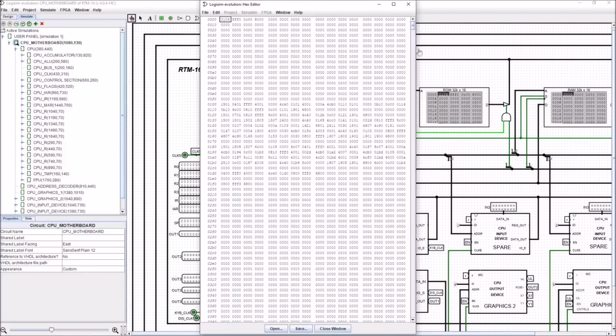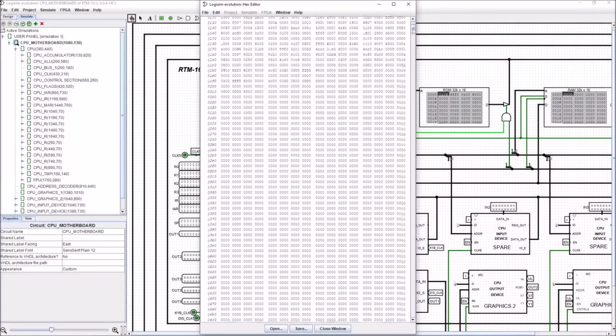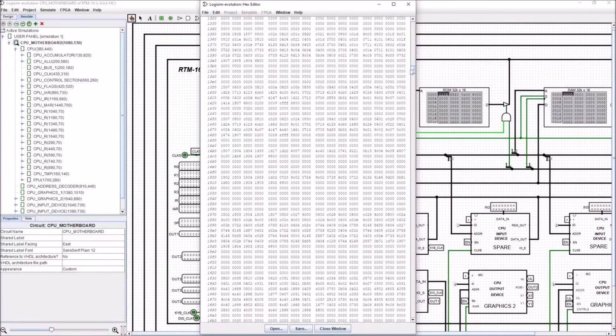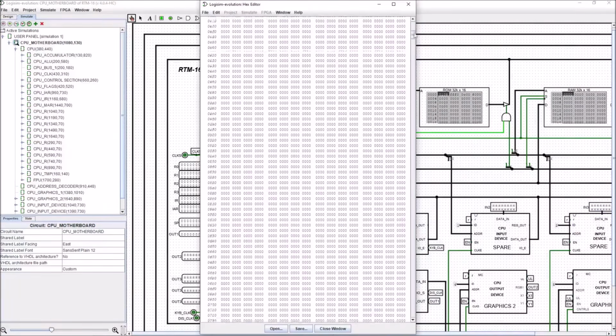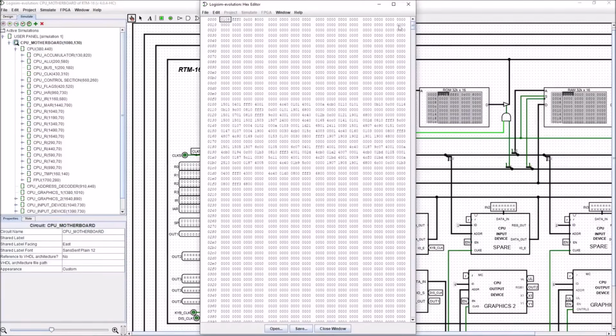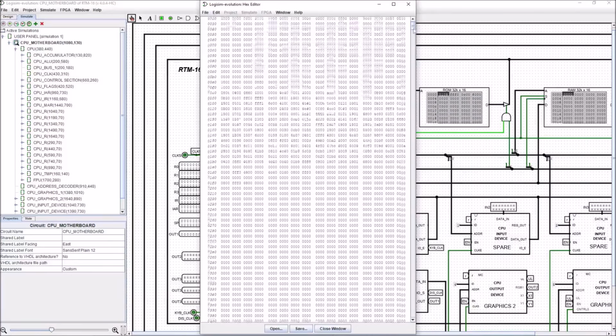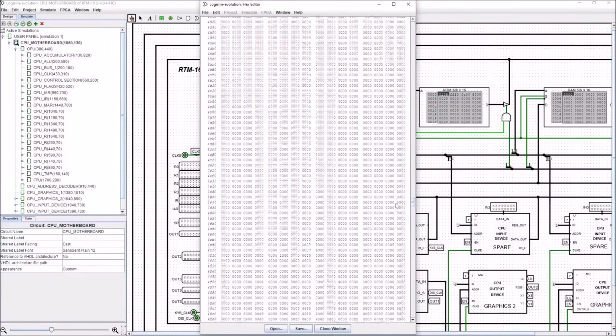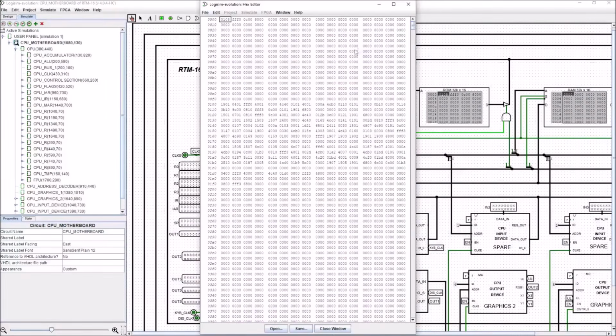So whenever we generate, for example, our floating point library, we're going to have the routines existing in a particular place in the memory within this ROM. And then if we generate our graphics library, it's going to exist in a different place within this ROM. And what we want to make sure is that whenever we generate these libraries, we don't have one library accidentally overwriting another library.